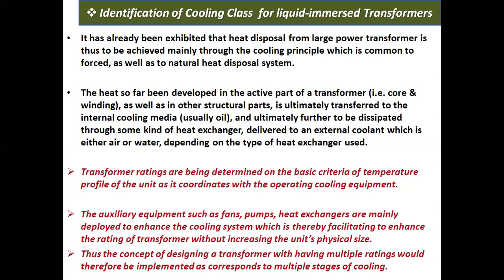Transformer ratings are determined on the basic criteria of temperature profile of the unit as it coordinates with the operating cooling equipment. The auxiliary equipment such as fans, pumps, heat exchangers are mainly deployed to enhance the cooling system, thereby facilitating to enhance the rating of transformer without increasing the unit's physical size.